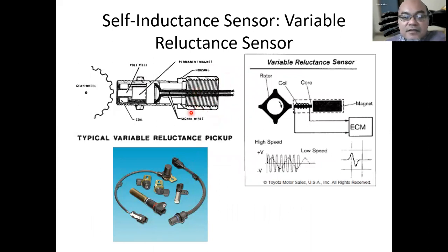This is what we meant. In this figure, it is illustrated where the coil is and the armature is. This is the coil, in the middle is the core, and we have another armature, a permanent magnetic field, usually made of either a permanent magnet material or a magnetic material wound with electrical current to make it an electromagnet, a magnetic source.